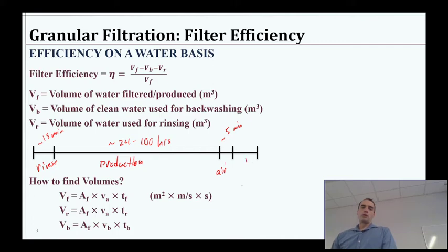And then our backwash, again, typically takes something like 15 minutes. So overall about half an hour or so per cycle is spent offline, not filtering water.